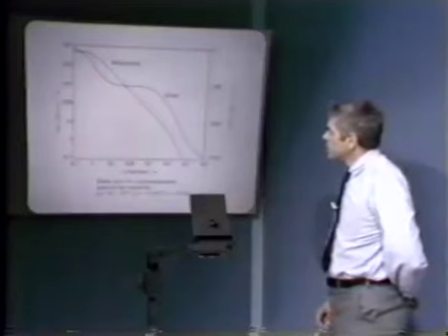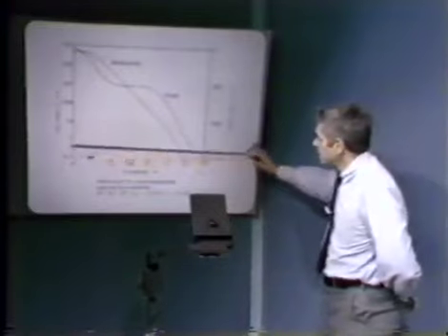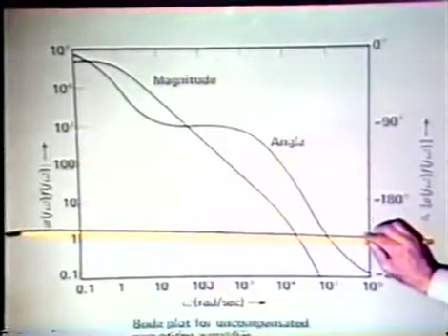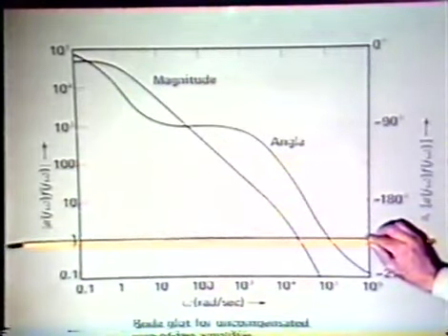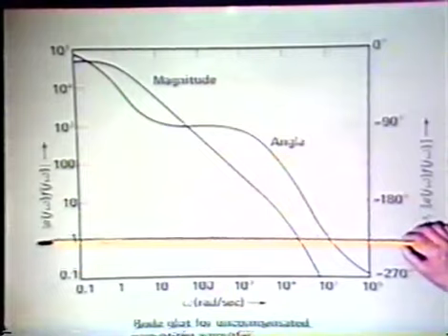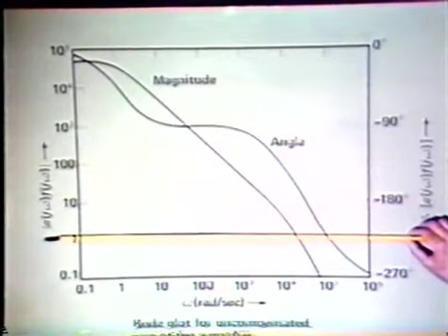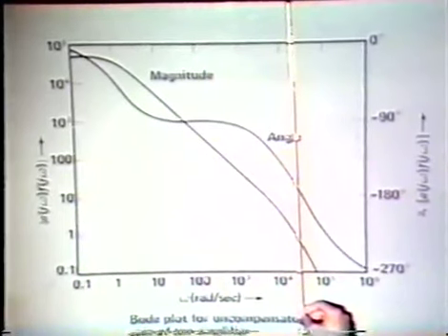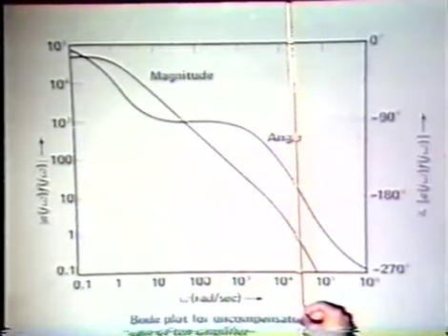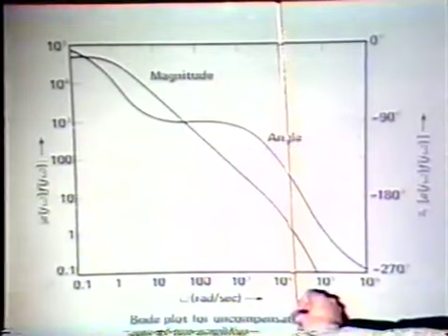And if we look at the phase margin of this configuration, recall that what we do is look at the unity gain frequency, the crossover frequency, the unity gain frequency associated with the AF product, which is right here, and that frequency, if we do it with some accuracy, works out to be 2.4 times 10 to the fourth radians per second. So this is about the unity gain frequency on our plot.